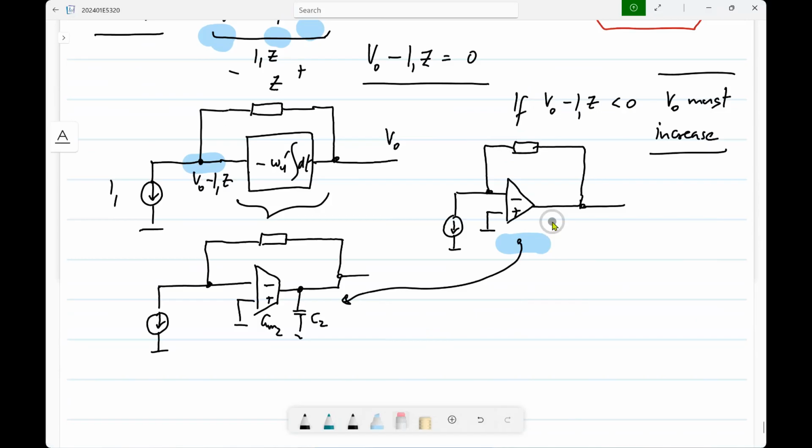What is it? It's basically the standard current controlled voltage source or the transimpedance amplifier. So instead of connecting the impedance Z across the current source, you make a transimpedance amplifier so that you have a better current to voltage conversion. Now, of course, you won't have the ideal op-amp to put here, so you have to use whatever op-amp you have, which is the single stage op-amp.